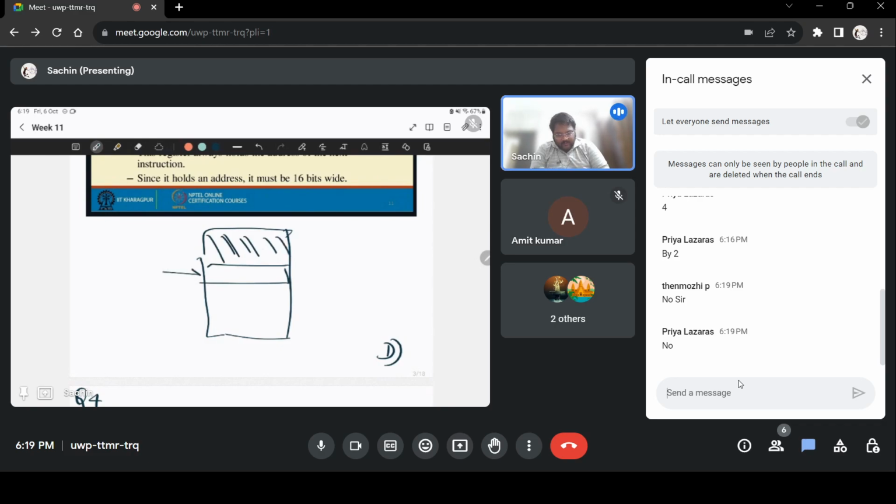So at this part of memory, this will have some address. Say this is 1000A, that's it, in hexadecimal. So here one instruction will be stored, and the next instruction will be stored here in the next address. The third instruction will be stored in the next address, and your set of instructions will be stored in a few address locations. So that constitutes your program.